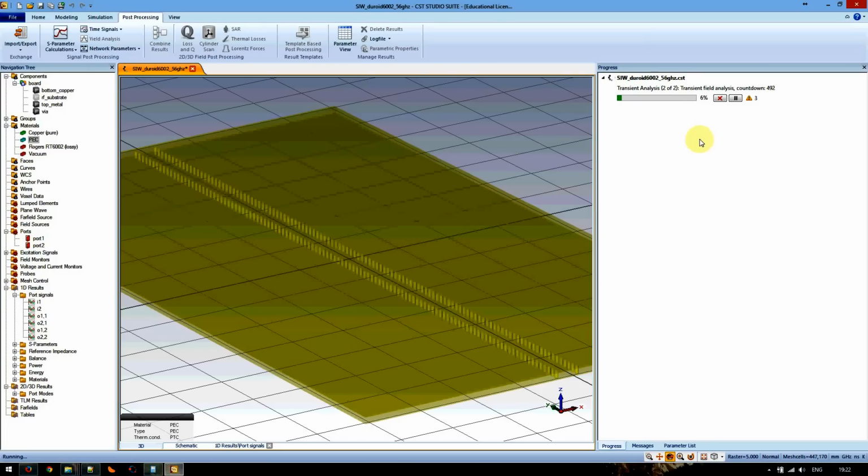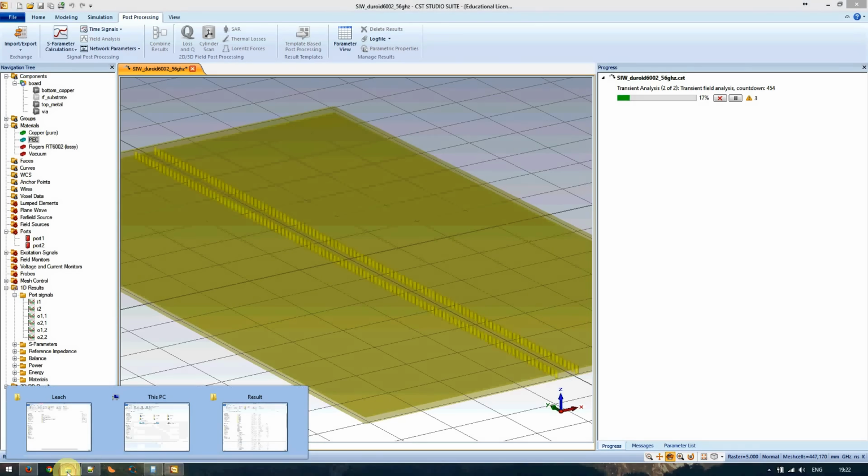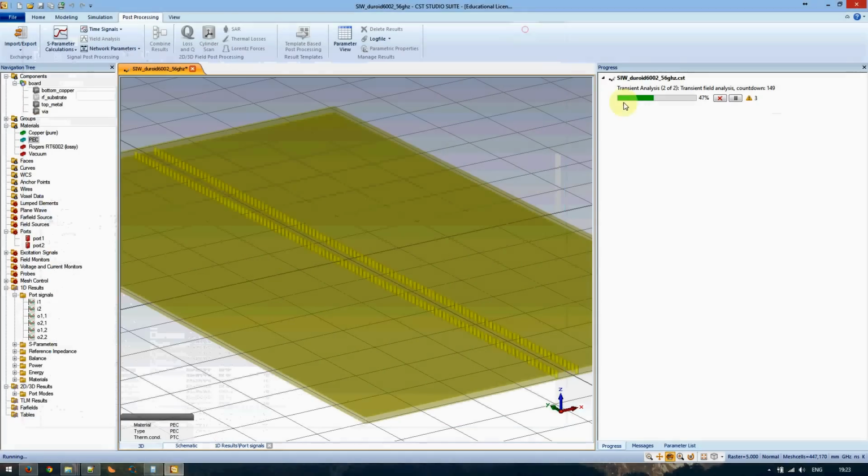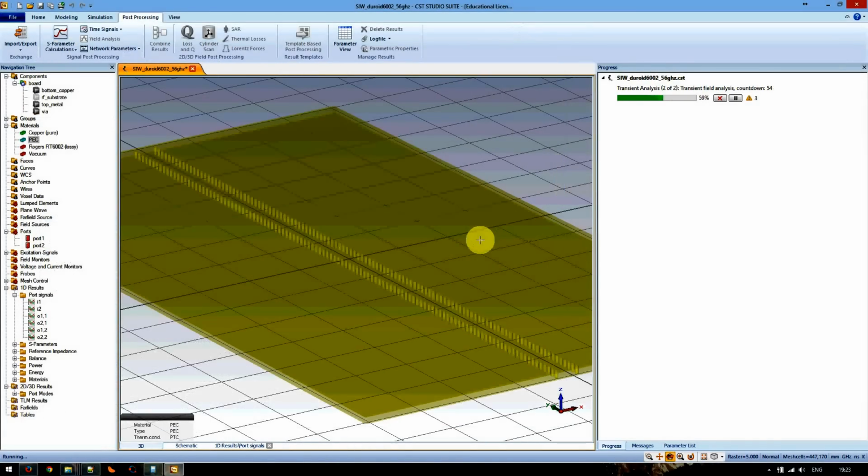Okay, you will need to play around with CST to find some settings. With every model, it's different. I've mostly worked with SIW at lower frequencies myself. 56 gigahertz is a little bit high for me, but quickly enough you'll find some settings which are comfortable for you. For example, at 56 gigahertz, a 40 millimeter or 70 millimeter long board is far too long, and no real system will end up being that long. So it's probably a bit overkill. I just wanted to demonstrate it for demonstration purposes.